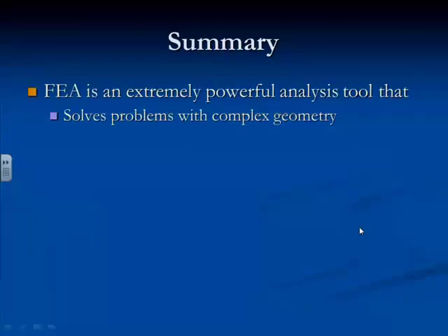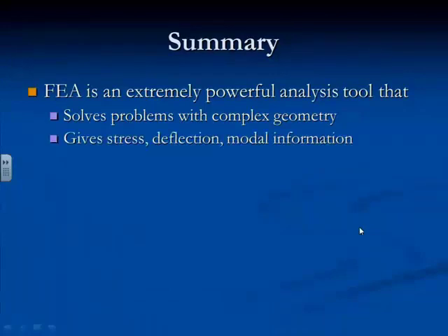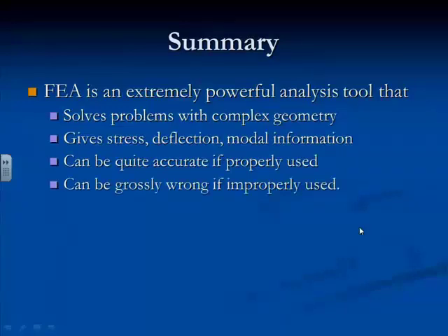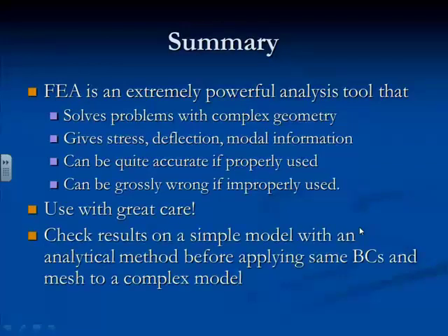Okay? So to sum up then, it's a very powerful tool. And like any powerful tool, you can get powerfully wrong answers out of it. It handles complex geometry. That's the beauty of it. And in combination with a CAD system, and they're all married to CAD systems, because you can take your CAD model and move it over into Abaqus or ANSYS or whatever and mesh it and turn the crank and put your boundary conditions in and get your results very nicely. I get stress, deflection, and modal information out of it. I can get really good answers if I'm using it right, and I can get really bad answers if I'm not. So you've got to use it with care.